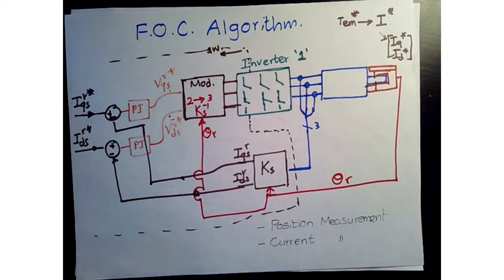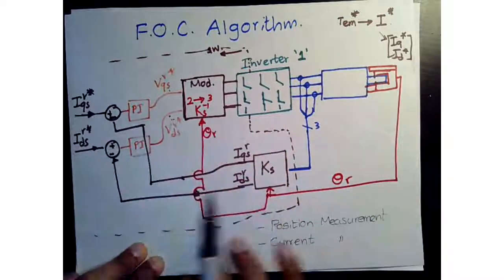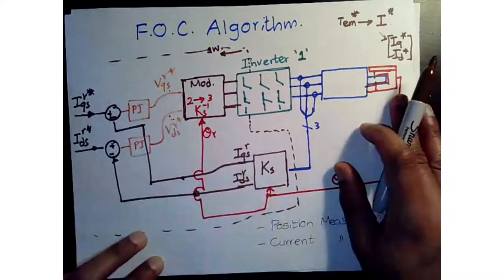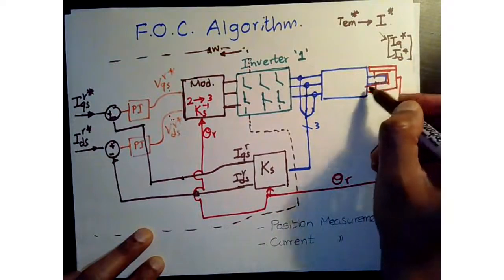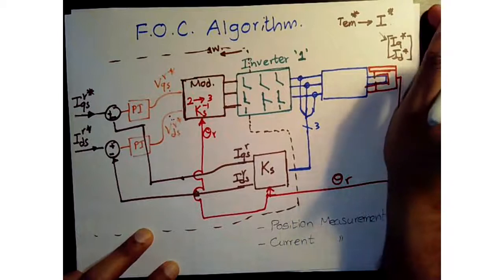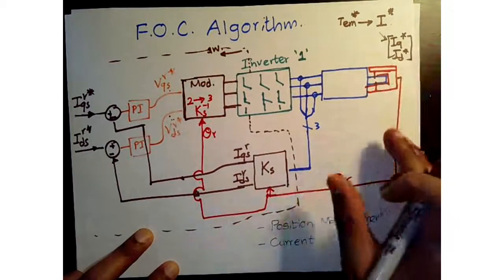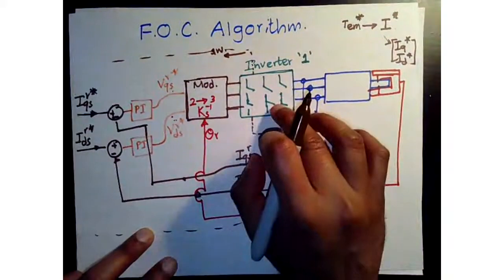Okay, and if you want to do that, one cautionary step: you can see that we are not controlling the speed here. So if you maintain a certain torque, this could speed up. Theoretically speaking, the speed could increase to infinity, right? But you have a limitation in your DC bus voltage for the inverter that we don't see here.